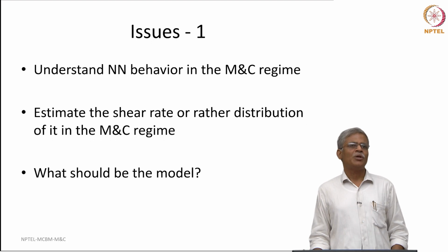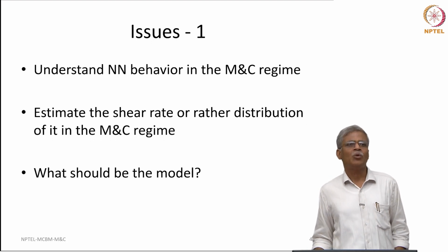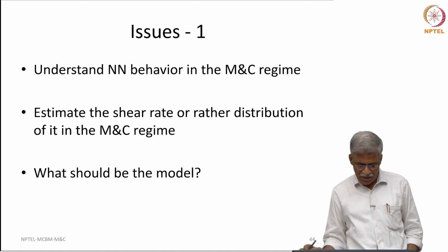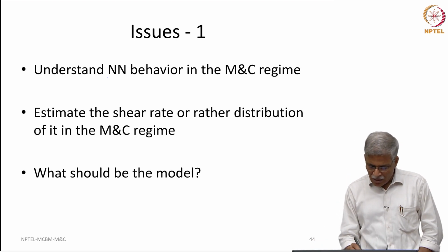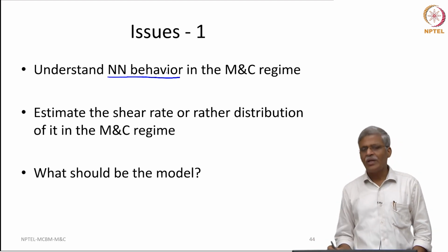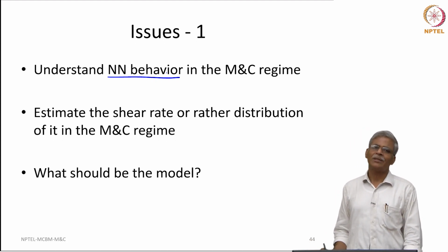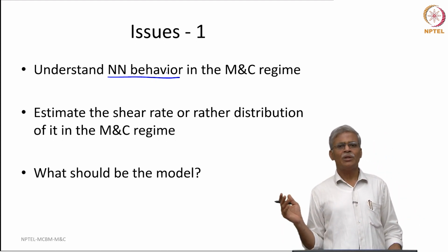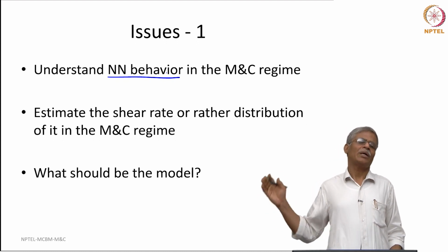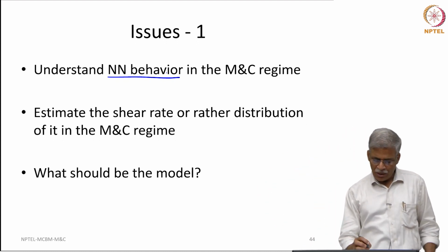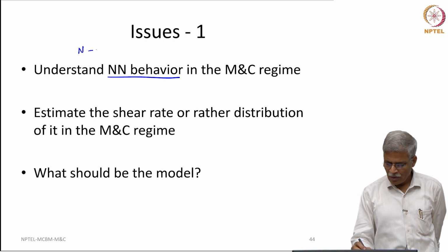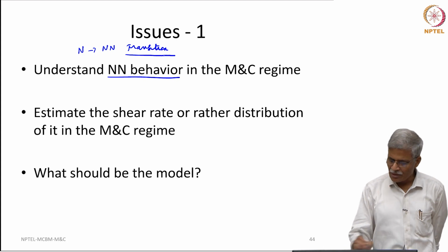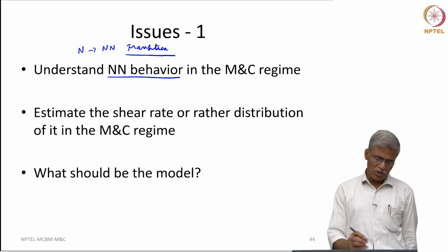first and foremost thing, if we really want to understand something about the mixing and compaction temperature, we should understand non-Newtonian behavior. We really cannot get out of the fact that the response of the material during the mixing to roller compaction is a Newtonian, non-Newtonian transition. So, we need to understand such transition. This is the first one.